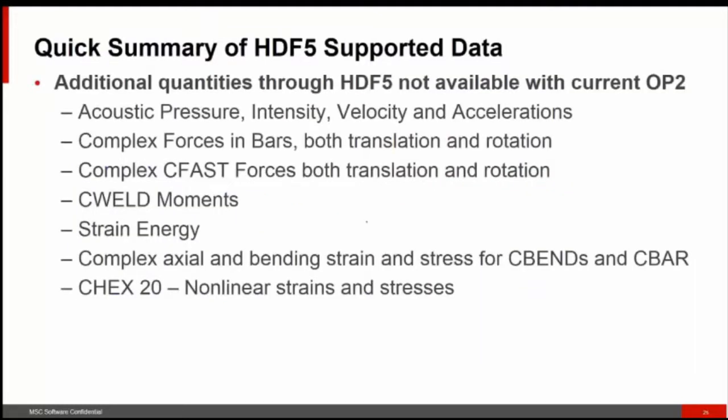These are the additional quantities and outputs that were not available in an OP2 currently, and so are available now using the HDF5. A lot of enhancements to acoustic results, so acoustic pressure, acoustic intensity, velocity, or acceleration. Also complex forces for bars in both translation and rotation, or complex forces for CFast elements, connectors.